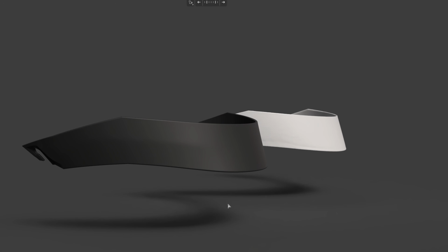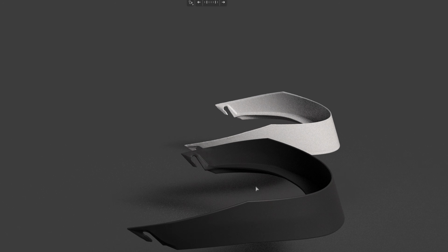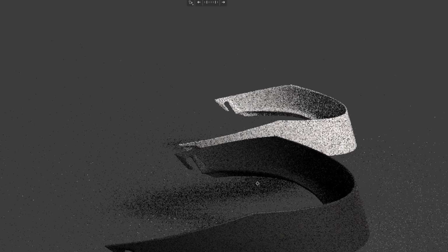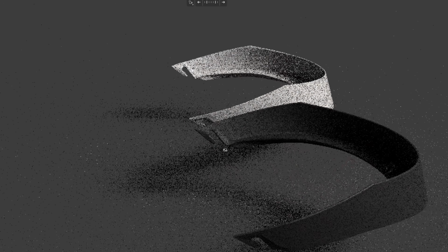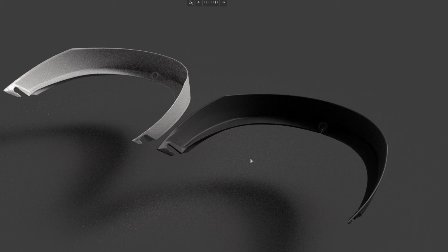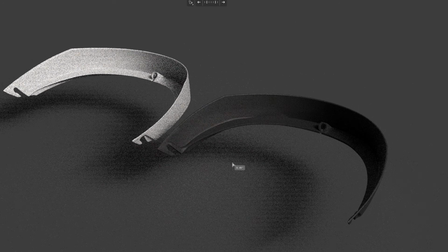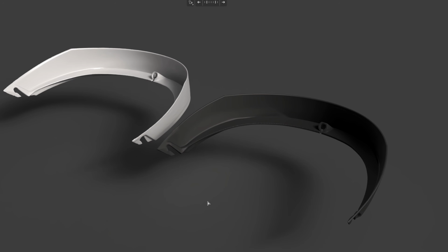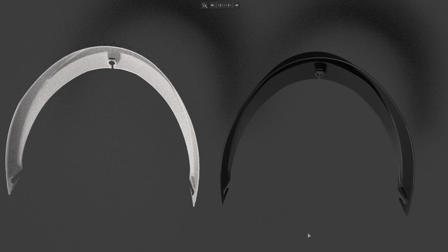In this case, the reverse engineered spoiler has a thicker wall for FDM printing. That's something you can easily adjust in CAD, but you can't add wall thickness directly to a mesh scan data. Next, I print this out to see how the loft surface looks when printed.